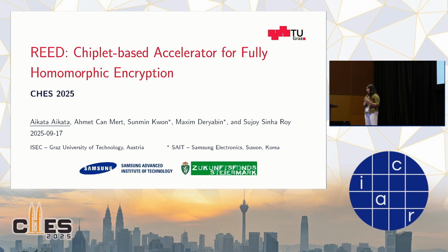Yeah, we have a simulation model, and we assume that HBMs can offer this amount of bandwidth, and that's why we have some on-chip cache to handle the buffering in between, and we have the same for the inter-chiplet. So this UCIe interface technology works for communication between chiplets? UCIe is for inter-chiplet, and then for HBM to chiplet, we have the NoC and these physical layers, which exist for connecting them. But yeah, we just use them as simulation models. Okay, thank you.